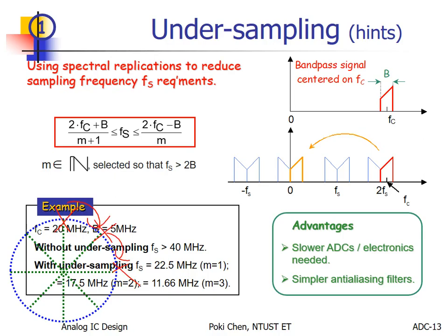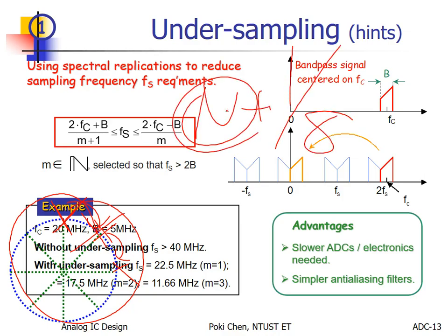But I cannot operate at such a high frequency. No worries. The first sample here, the next sample, oh, there. The same. You get exactly the same samples. I don't care how many periods it rotates. I don't care. Only if it is the same. That's it. That is the idea for undersampling.